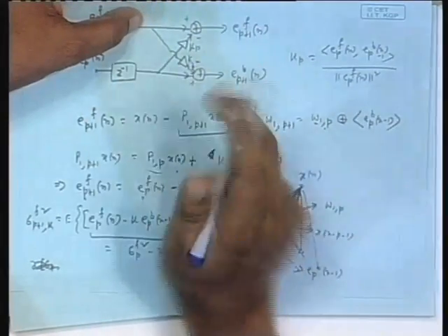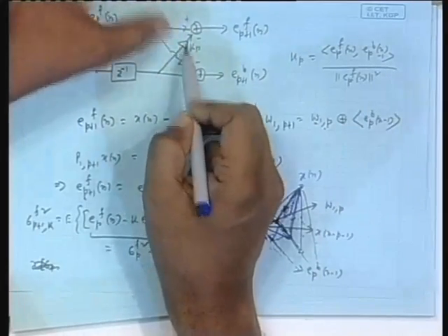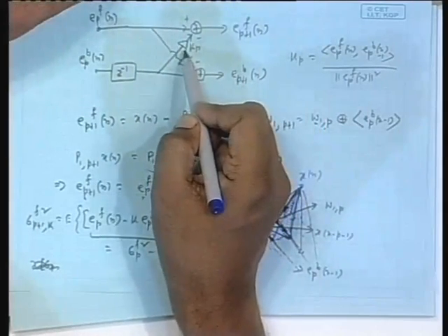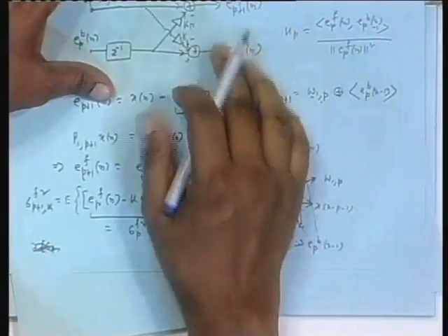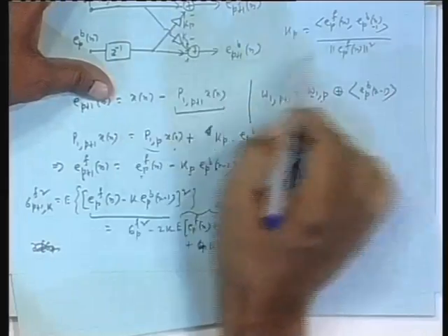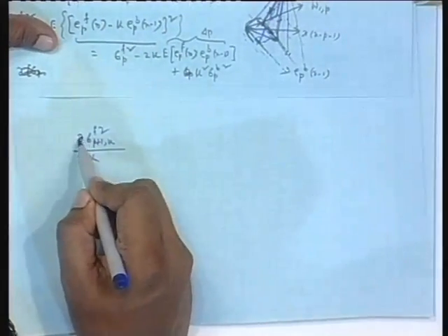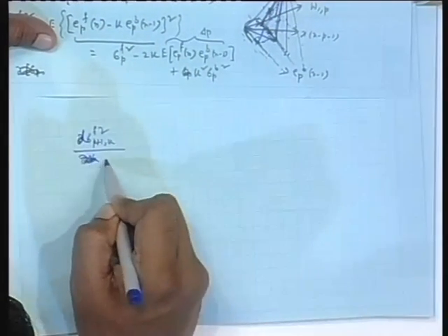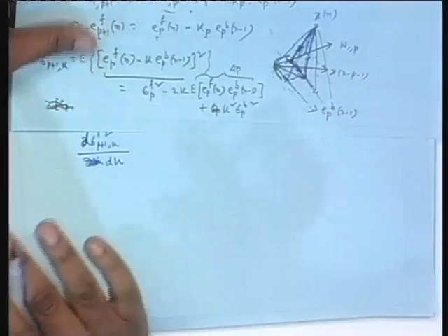It is like a lattice stage, one term, another term. Like there I had xn, xn minus 1, it is just one component, another component, linearly combined, only one filter coefficient, which I am calling say k. Instead of kp, kp is the optimal one, I am assuming I do not know, so I am putting it arbitrarily k, and by steepest descent I have to find out what the kp is, that is a different matter. So, you can drop this notation also, it should be d according to me. You know this difference, na? When partial derivatives come and when, so this should be d.